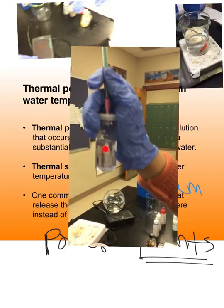So that purple tinge tells you that there's still some dissolved oxygen that is not combined with the indicator here, right? So at the point when this completely turns colorless, that means you've used just the right amount of this titration liquid here to completely neutralize, right? And there's a little meter here that'll tell you the amount of dissolved oxygen that there must be in the test chamber, right? And it ended up coming out to about 7.5, right?